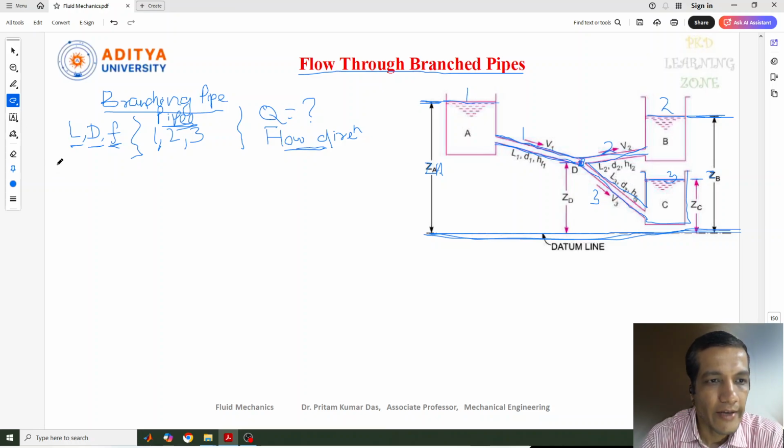So for example, when it is flowing through pipes, we see when areas are given. One more thing also, velocity I have not told here. So velocity also needs to be considered here. For this pipe, velocity V1, L1, D1, HF1. HF1 is the head loss actually, and F is required to find out the head loss. So second pipe, similarly, velocity V2 and L2, D2, HF2. And similarly for pipe 3, velocity V3, and the related parameters L3, D3, HF3.